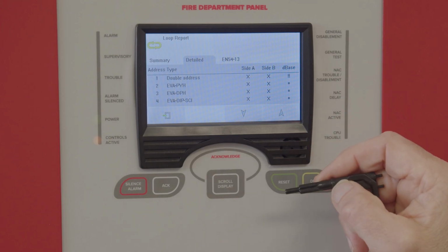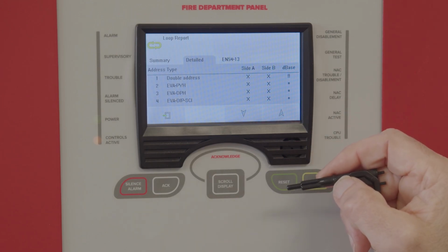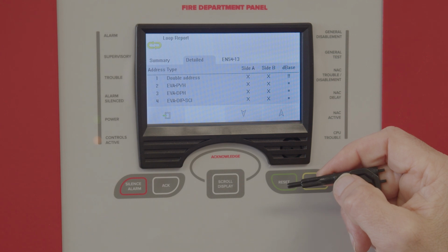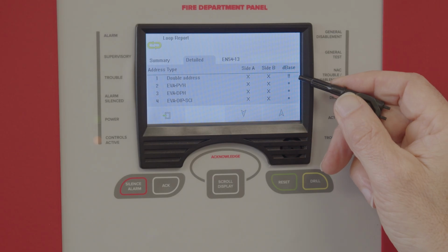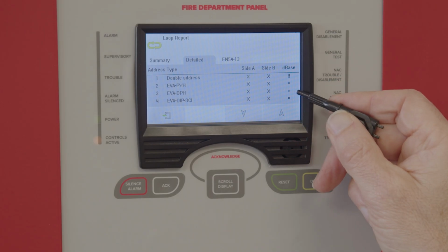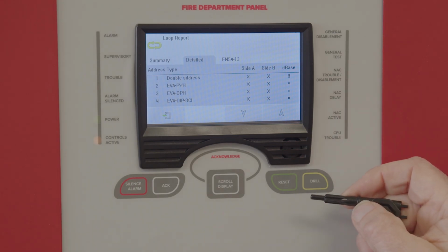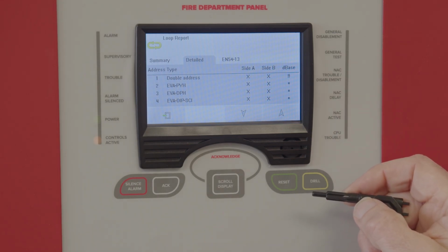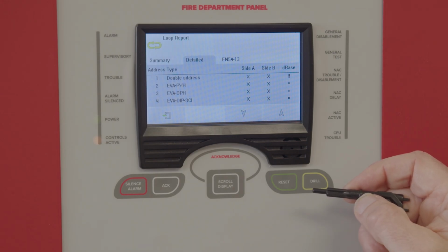Database: this shows if the device seen is different to the previous database. Double exclamation marks indicate the device type was changed. Equal sign indicates it is the same as previously configured. Devices listed as unknown items are not learned into the panel database. They are newly launched devices not supported by the current firmware version in the panel. It will be necessary to update to the latest version to support these items.